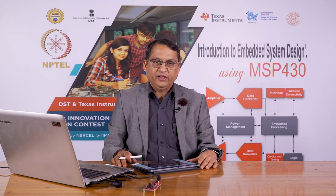Alright. So, now we know that we have so many registers to deal with. We have a direction register, we have an input register, we have an output register, we have a pull up enable register, and we have select and select 2 registers. These many registers you have to write. Now, thankfully, many of the registers have friendly default values, that is values at reset are helping you, so that these are configured as port and they are usually configured as input.